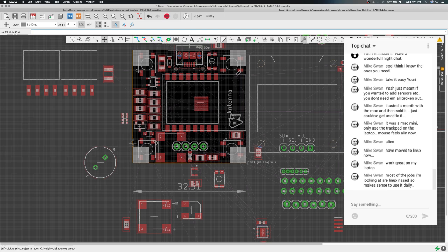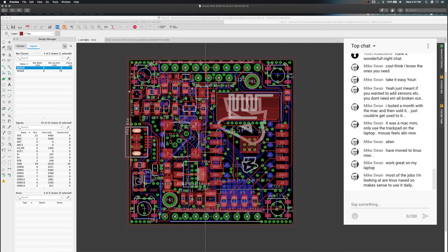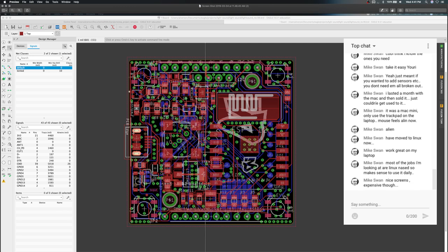I also put it in the front. In my previous design, I put the buzzer here with the opening port here, thinking that the jack, whatever you put this in, is going to have an opening for your USB cable or your power. So you'd have a hole in an enclosure, and that's where the sound would come out. Well, it doesn't really work that way. You don't think of a piezo moving a lot of air, but the frequencies it makes just don't come out of an enclosure. So you have to have a little hole somewhere.